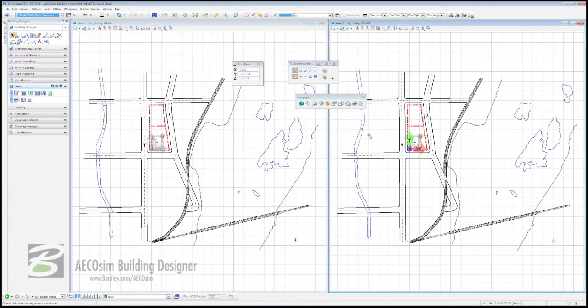Georeferencing is just one aspect of how we can control, collaborate, and move towards creating a 3-dimensional terrain model. Building Designer also has a unique partnership with the likes of Google Earth, and that's what we're going to be using now to help us create our terrain site. Before we do that, we may want to look at some of the settings we may need for this particular session. We're going to come on this icon here, third in from the right, Google Earth Settings.